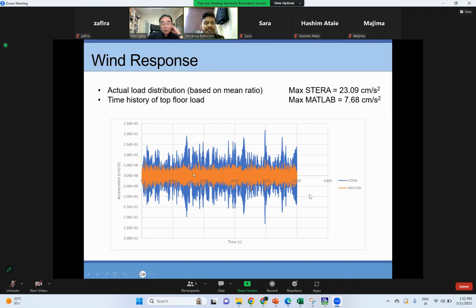Earlier I was showing you the results of my wind data in my first meeting, when I was saying that the wind response is very high as compared to the uncontrolled response. Then I reduced the time step, and I actually got a wind response that is less than even half of that. Because it is highly nonlinear, the trilinear model which I have prepared requires smaller time steps. But this program in MATLAB is taking 8 hours to give me the results.